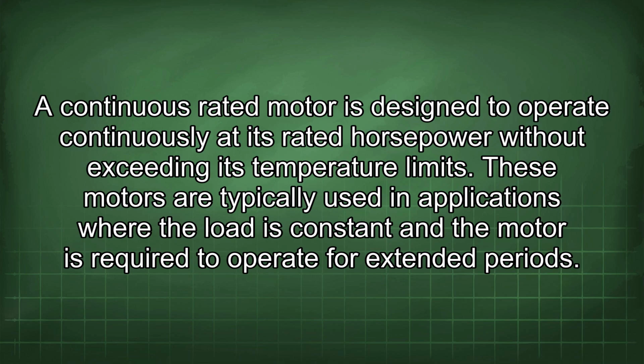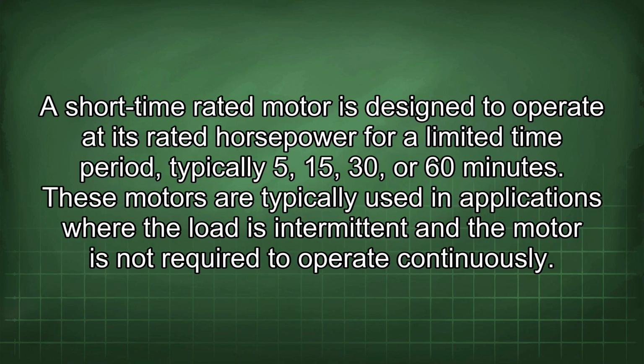These motors are typically used in applications where the load is constant and the motor is required to operate for extended periods. A short time-rated motor is designed to operate at its rated horsepower for a limited time period, typically 5, 15, 30, or 60 minutes.